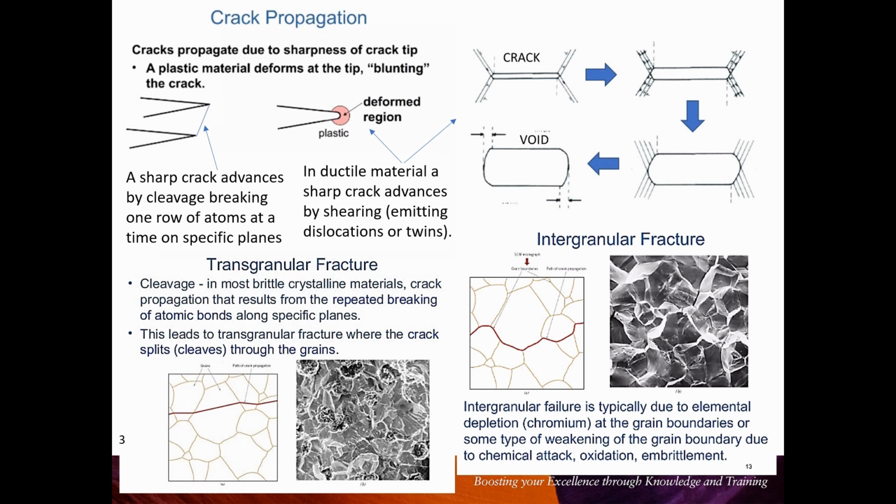So although body-centered cubic materials are much more brittle, especially when irradiated, than austenitic alloys, I'm actually not going to talk about them today because they're generally not used in the reactor core because of the low temperature embrittlement. So the worry for those materials is that if you ever drop the temperature, shut down the reactor, and they were under some stress, they could still potentially break because they have lost their ability to absorb any energy.